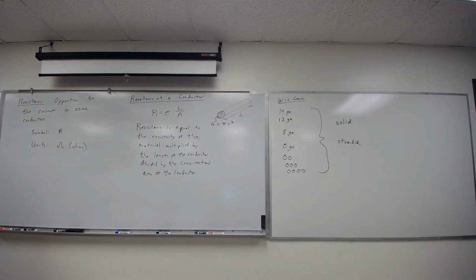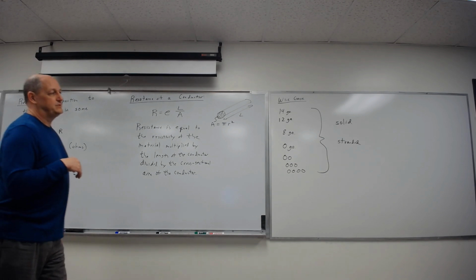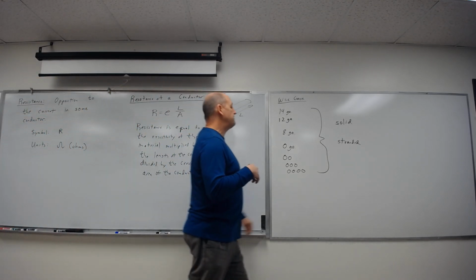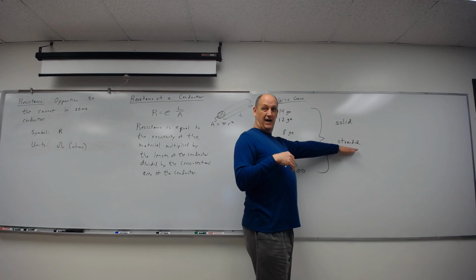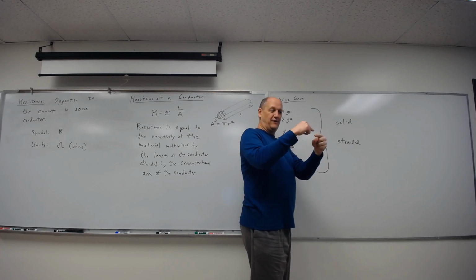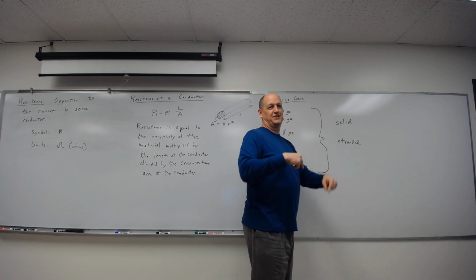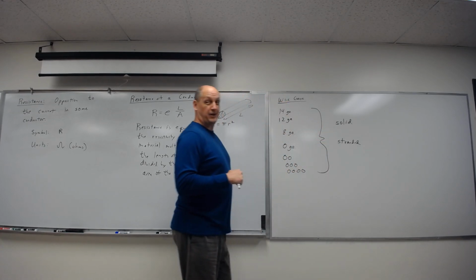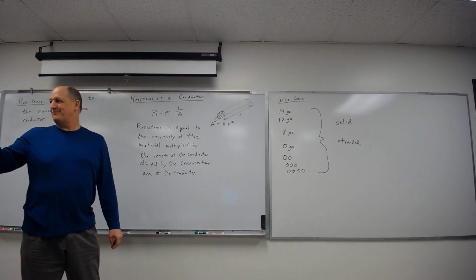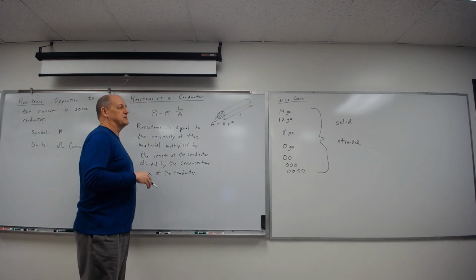If an individual wire breaks, it's still probably okay to carry current. I have some of that in here for us. I would encourage you not to try using it too much because it's a little harder to work with. It's easier to bend and move, but it's harder on the ends because you have all those wire strands hanging out. I don't really care if you try to use it, but there's some wire over there. Use it for speakers or something like that.